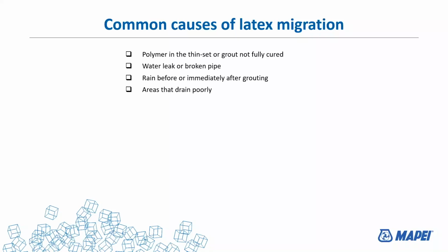There is one 6-inch drain in the middle of 4,000 square feet of Indiana limestone. The floor was pitched to the house, not away. They live on Tampa Bay, overlooking the water. There's a saltwater pool with saltwater fountains on a saltwater bay, and they have an efflorescence problem.